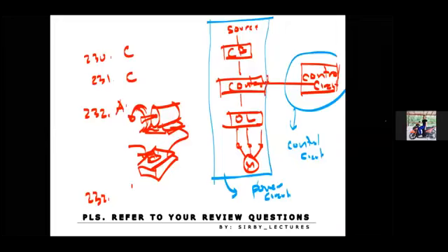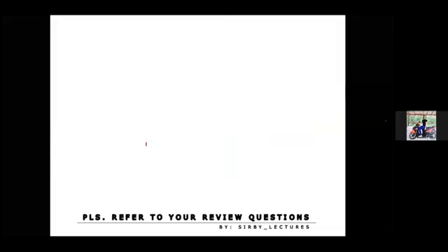And for the term plugging, this refers to a method of stopping a polyphase motor quickly by momentarily connecting the motor for the reverse rotation. So when I click this, instead of rotating clockwise, it rotates counterclockwise immediately. Okay, so if that's the case, that is what we call plugging. Letter B.